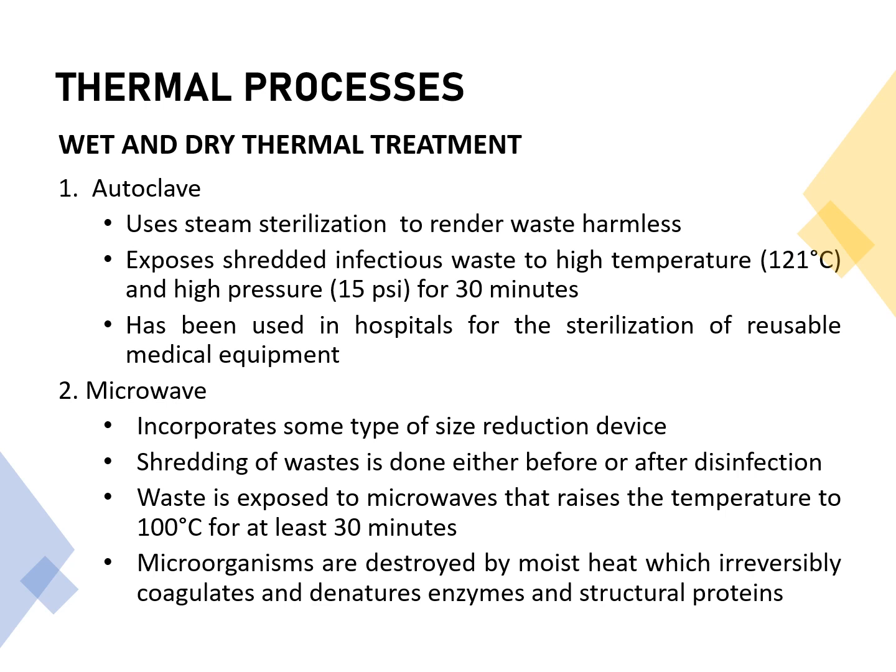So in using the autoclave, you have to expose the waste or infectious waste to a very high temperature. It's usually 121 degrees Celsius and high pressure of 15 pounds per square inch for 30 minutes or sometimes 1 hour. So it has been used in hospitals for sterilizing reusable medical equipment.